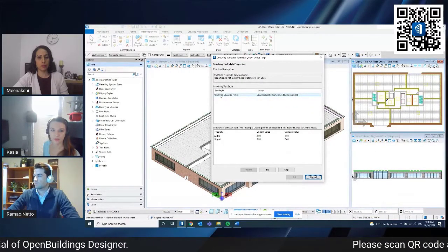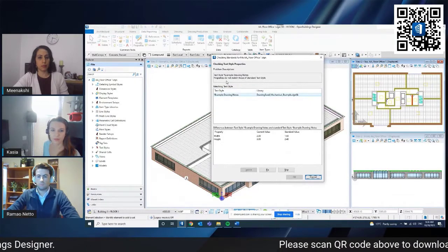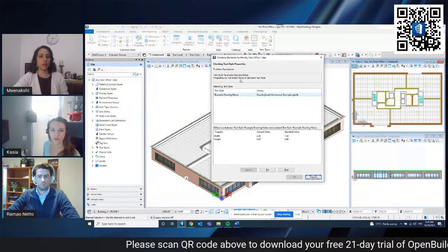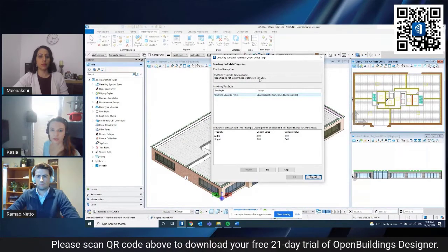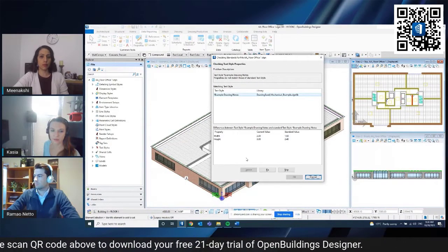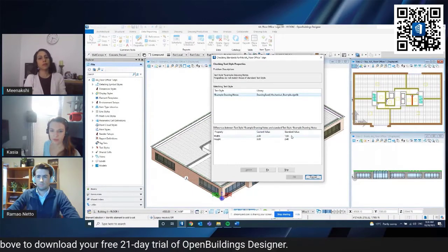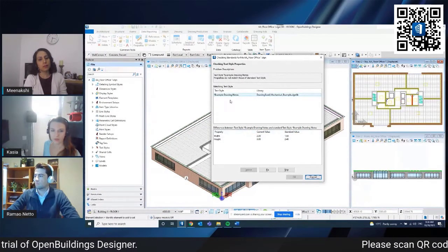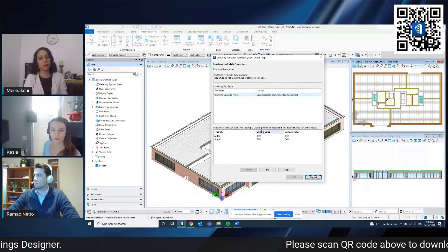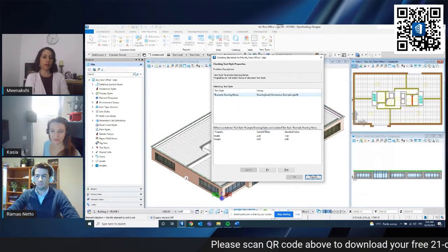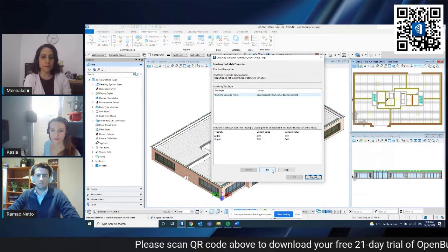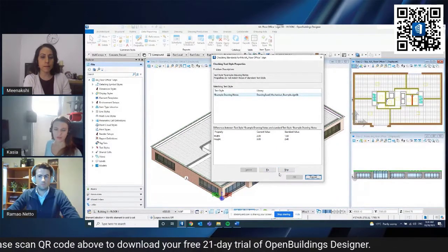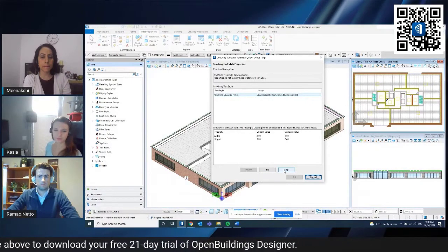I can see that the properties of the text style example drawing notes don't match those of the standard text style. So I can see the current value and I can see the standard value of the text style specified, and I can then fix this problem or I can just skip it, depending on what I need.